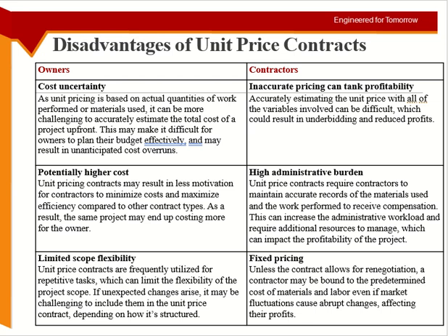Okay, in the unit price, you have to keep more record of your work because the client would say, okay, you are asking for the price for excavation. So show me your record, how much excavation you did. You have to keep the record. You have to keep the record of the concrete strength tests and so on and so forth. Okay, because you are not getting paid for the project. You are getting paid for each item. So you have to keep the record of each item separately.